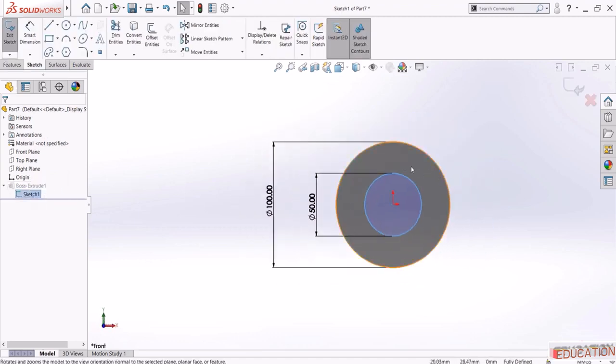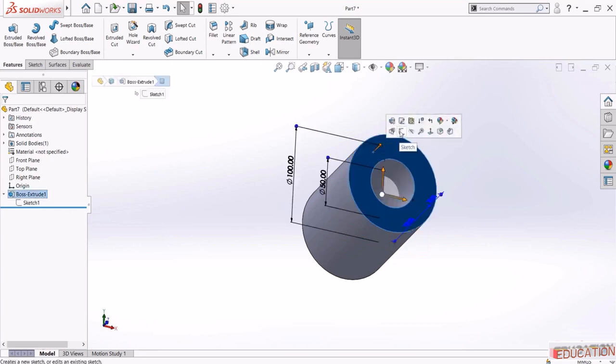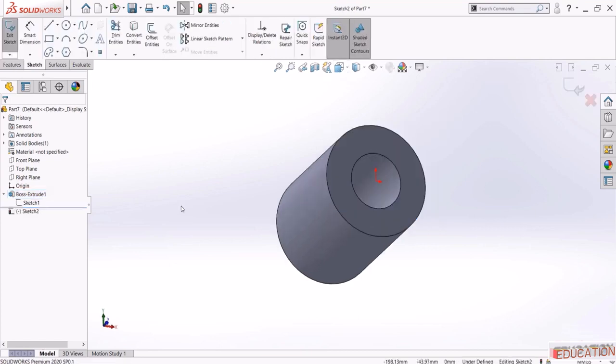which is this area. As we earlier discussed, you need a flat surface to start the sketch. So it's not limited to these planes. Now I have this flat surface. I can select this face, and here select sketch. If you don't have a normal view to this face, simply select the sketch from here, and then Normal To.